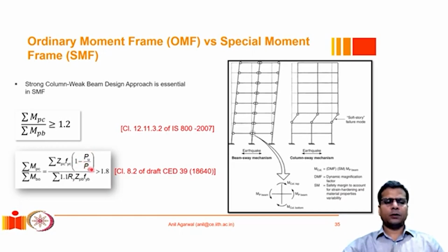So if you have learned how to design slender columns, you would have come across this expression, which accounts for the reduction in strength in a column because of the slenderness effect. Now, the only issue, in my opinion, is that the 1.8 factor seems too large. Maybe there is some rationale for that. We have to hear more from the committee to understand it fully.